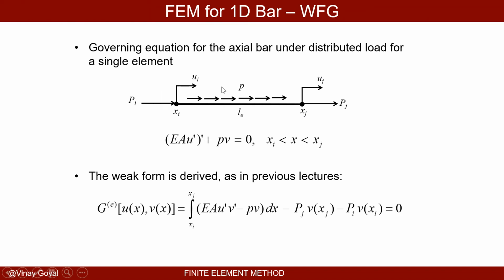If I look at the weak form of the problem that we derived starting from this equation, I multiply this equation, and that's an error, no V there. I multiply this equation by V. When I multiply EAU prime plus P, without the V, I multiply the whole thing by V and integrate by parts once. We demonstrated already in lecture 6 that this is the weak form of the problem, where V were the weight functions, right?